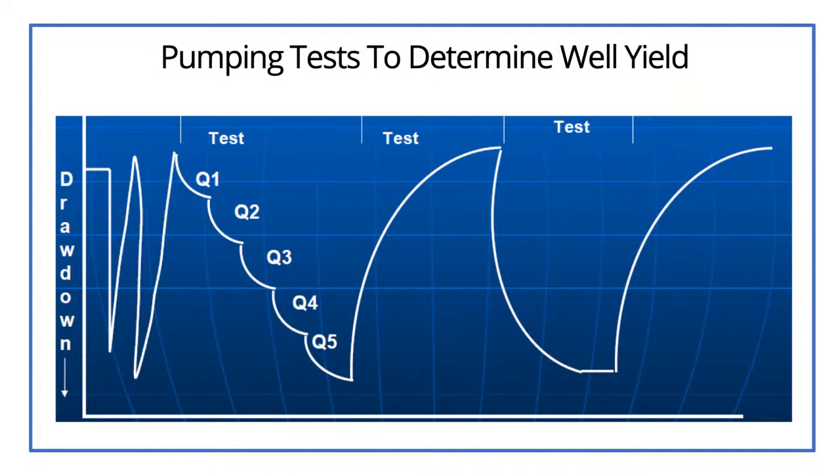We're going to do, there's several types of pumping tests. We're going to usually do some preliminary pumping to prep the well for the test. Then we're going to do what we call some step tests. And we're actually going to pump the well at increasing rates, no break in between, and we're going to see where our optimal rate is. Then we're going to let that recover back to our static water level that we've measured ahead of time. And then we're going to do a constant rate test, and that's going to be at our optimal rate that we've calculated from the step test.